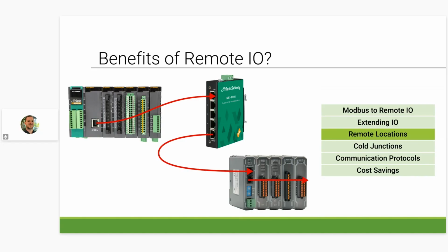Analog sensors can be used for measuring volumes in tanks, ambient pressure, or temperatures, just to list a few examples. The further the wires from the analog sensors have to travel to reach the PLC and local I/O, the less accurate the readings can be, which can greatly affect the outcome of the application since those readings need to be precise. With the use of remote I/O, you can keep the I/O as close as possible to the analog sensors, thus making readings the most accurate as well.